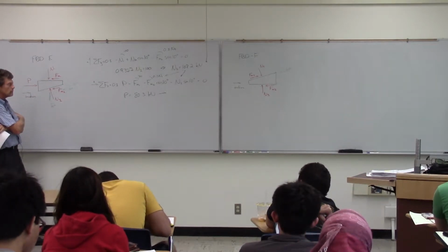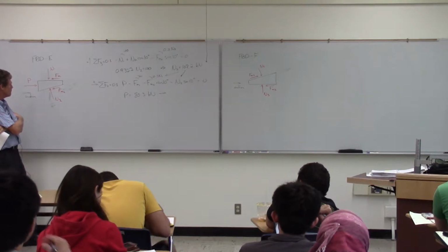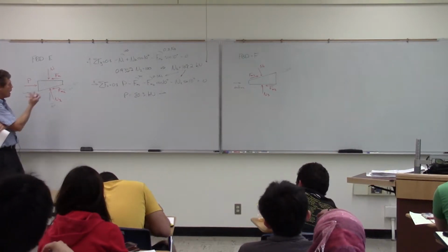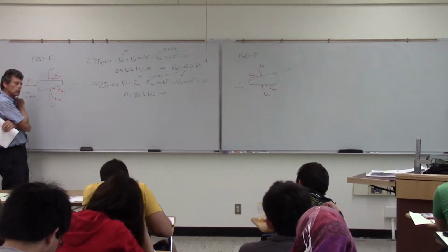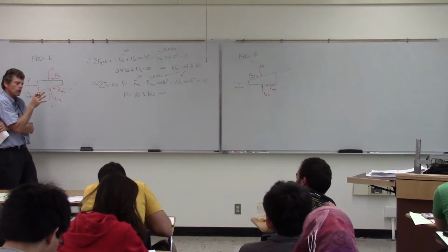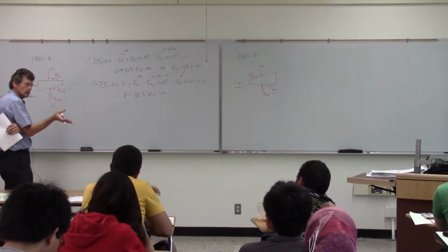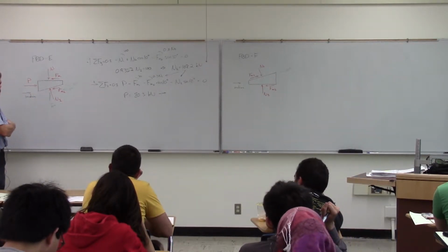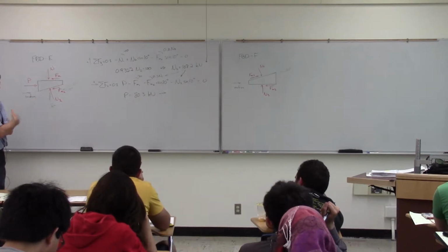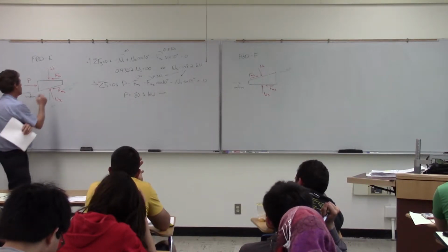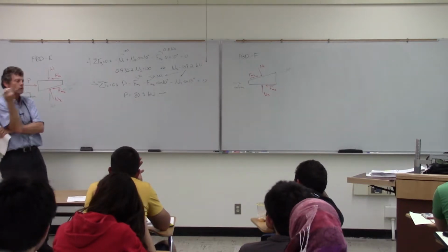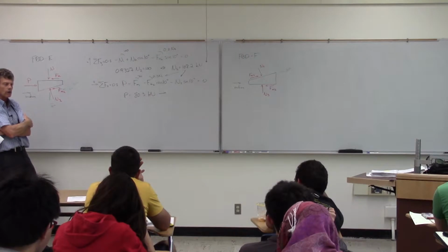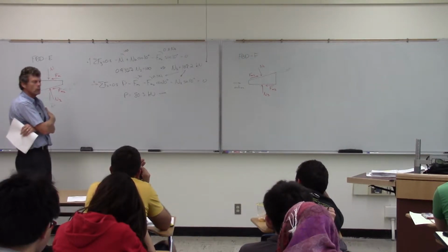I feel like there should be another force, like the force of that object's weight. That would be a possibility if they included the weights. Usually the wedges are so small in terms of weight compared to the load that they're moving, though. We usually ignore them. But you're right. If you want to be precise, we'd probably throw a weight in there, which, depending on the wedge, may then take us out of the force triangle, and we might have to go with the Cartesian system there. And that's why I'm going to show you both anyway.